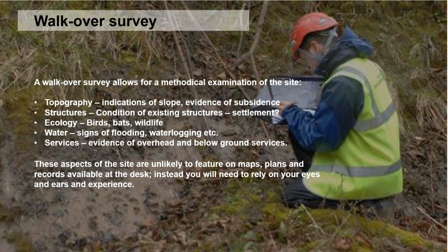A walkover site primarily lets you do an examination of the site, looking at the slope or the shape of the ground, which is the topography, looking at any existing buildings, looking for evidence of wildlife, considering how much water there might be on the site, whether there's ponding or water running through the site, and also services within the site.